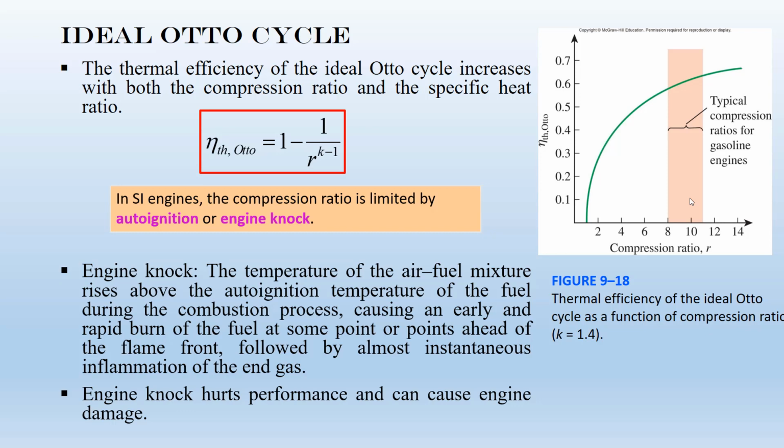So if we have the early and local ignition, what happened? A part of the energy of the fuel is lost. This is the first drawback of very high compression ratio. The other one is that when we have the local combustion, we have a temperature gradient over the surface of the piston and cylinder. This temperature gradient causes damage to the engine. So because of these two main drawbacks, we prefer to use the optimum value for compression ratio.